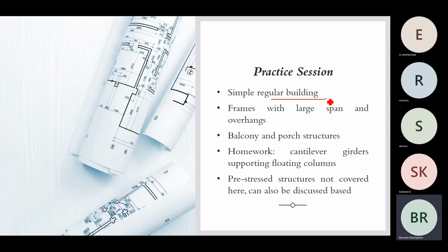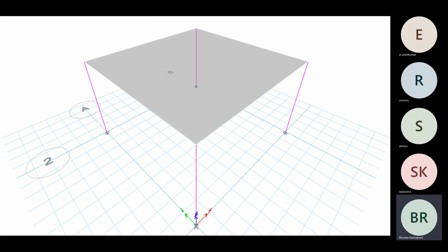So for a regular building, let us try to see where there are no overhangs, no cantilever in the horizontal and vertical direction, no projection is there, a simple type of structure. If we consider this as one sample and try to find the effect of vertical earthquake and horizontal earthquake and try to calculate it manually, then we will be able to find the difference. I leave it to you how you manually do it or do it in software, you will also get the results, but it is always better to create your Excel or do it with a calculator.